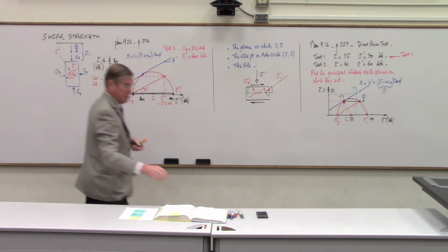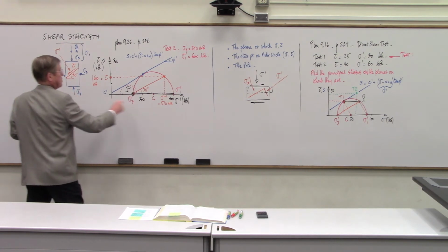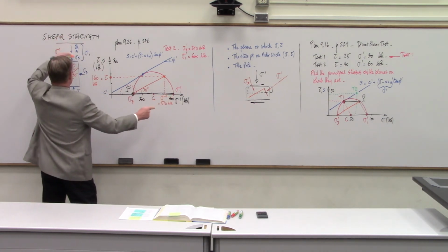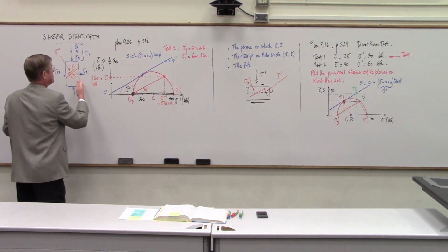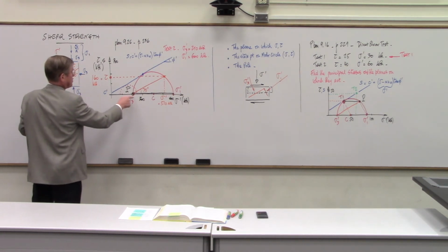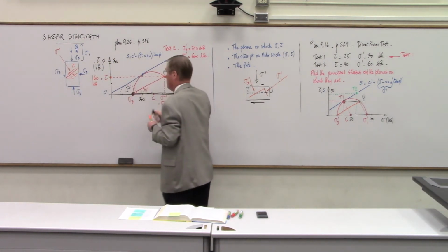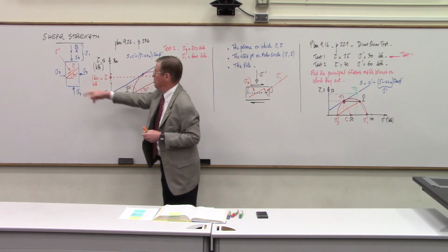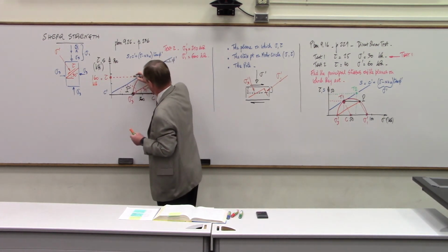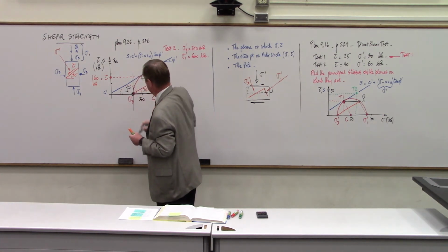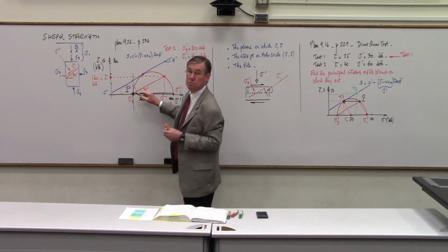I chose the horizontal plane here, and sigma prime 1, because sigma prime 1 was acting on the horizontal plane. I could have chosen another plane, another stress, which is sigma prime 3. In that case, the line would be vertical, the stress point would be sigma prime 3, and I would draw a vertical line that would intersect the circle at the stress point and the pole.